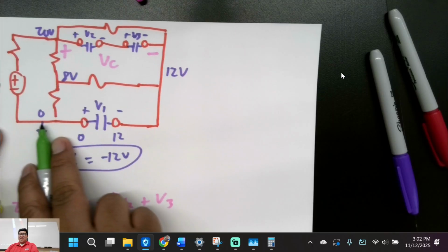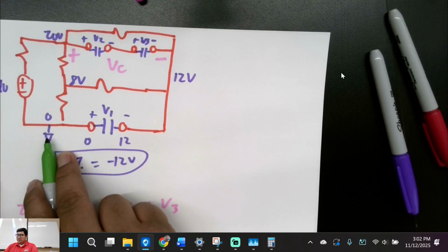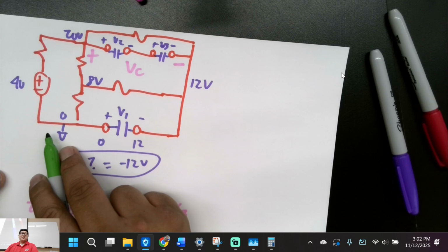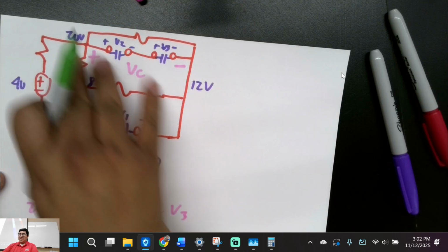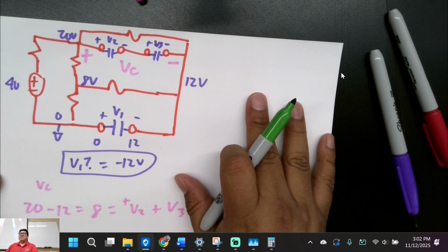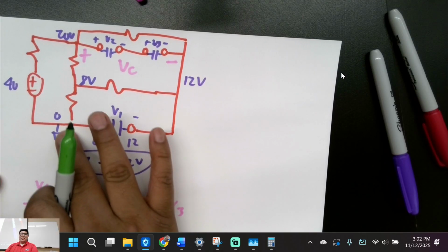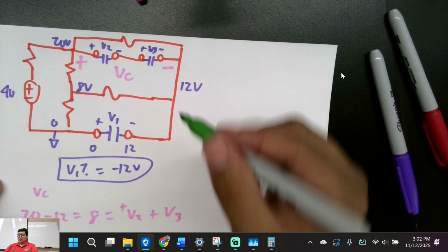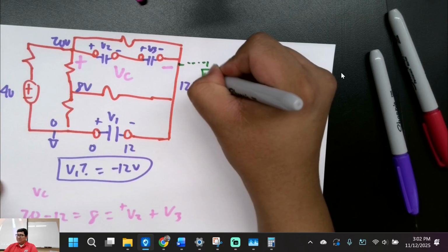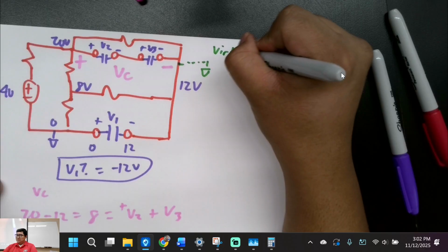Let's just say this ground right here, I'm going to add 1,000 volts. What happens to everything here, all the voltages? Goes up by 1,000. It's constant, correct? Does that make sense? This reference is just something to help us. So imagine if I'd made some kind of ghost reference here, some virtual.